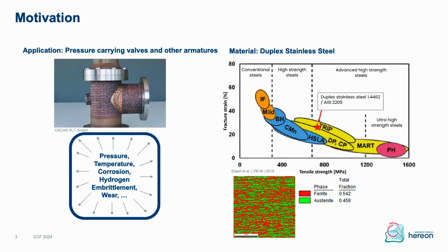As a material for these applications, we are currently investigating the use of duplex stainless steel, mainly because it has superior mechanical properties when compared to the conventional austenitic stainless steels, almost 2.5 times the yield strength, comparable ductility, and superior stress corrosion cracking resistance. The origin of the superior properties of this material is in the duplex austenitic-ferritic microstructure, which needs to be kept at a balanced ratio of approximately 50-50, where the ferritic phase increases the strength and the austenitic phase increases the corrosion resistance and toughness.